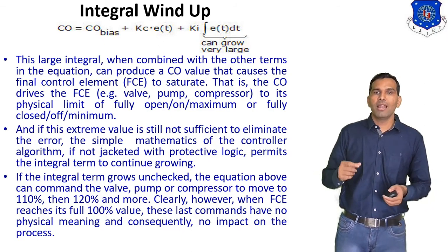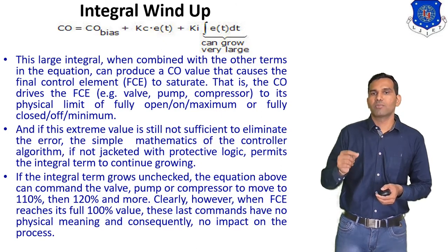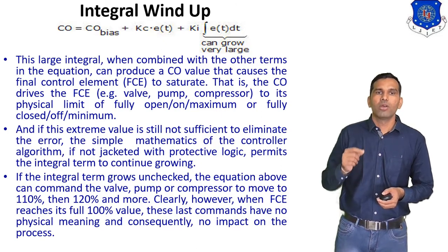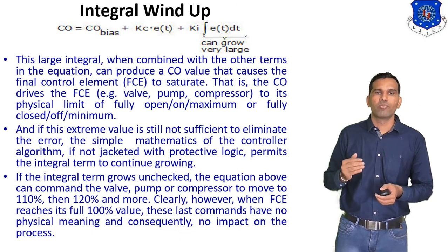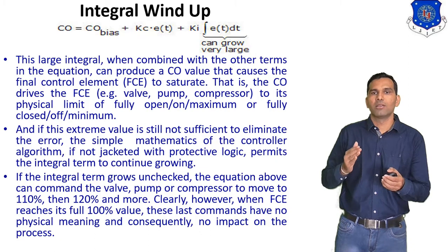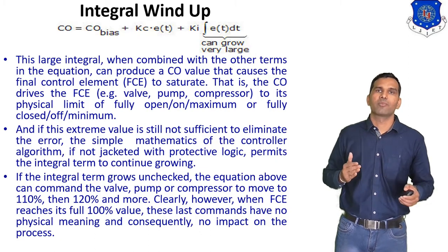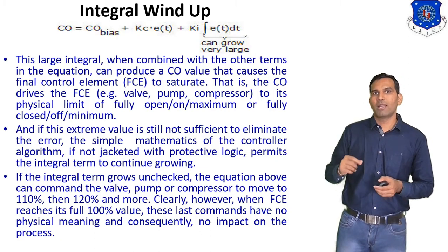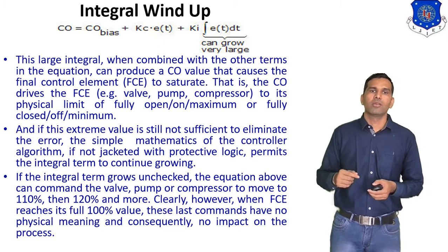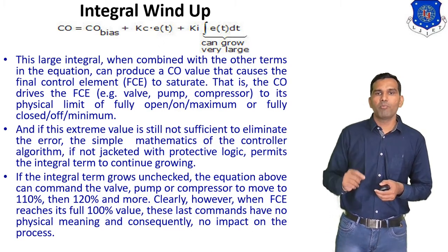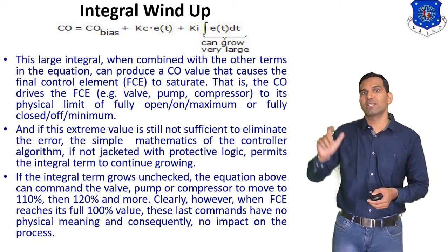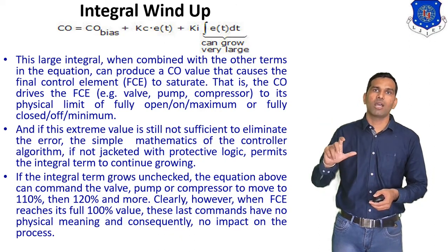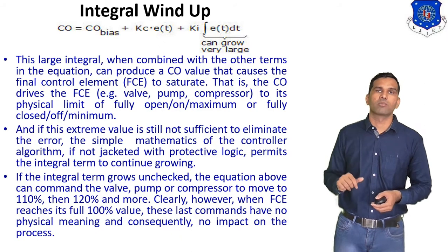Clearly, once the FCE, the final control element, reaches its full 100% value, the last commands have no physical meaning, that means 110, 120. Consequently, there is no impact on the process. That is known as the saturation effect. It does not affect the controlling system.